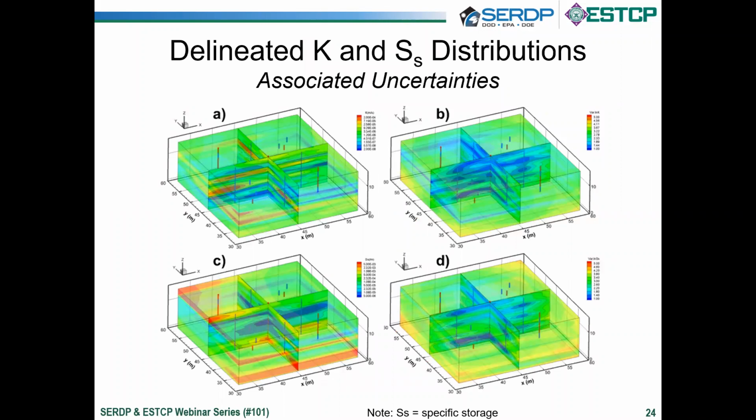So when we consider the 7 pumping tests and invert the system during the hydraulic tomography, the result gives us a depiction of the 3-dimensional distribution of hydraulic conductivity. And in addition, we are using the transient information, so we obtain the spatial distribution of the specific storage as well.